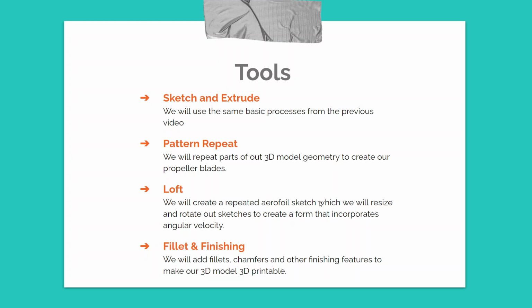So the loft is where you set up 3 sketches in 3 parallel planes. You can add more if you want. If you do a loft between 2 planes, it'll be a straight kind of curvature between the 2. If you do 3, it'll average out, 4 and so on. When we do aerodynamics next year in our aerofoil design for our wings, we'll be using lofting again, okay?